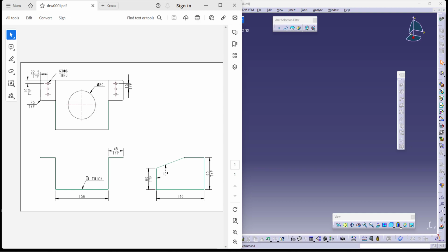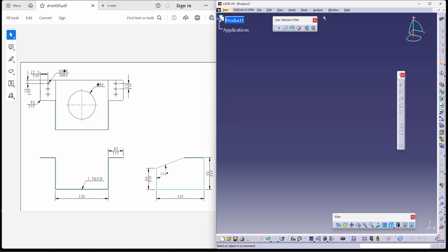So the sheet is actually of one thickness and the overall size is 160 by 140, and there are two other walls which are added, 190 by 60, and small walls over here for clamping purposes. Now, to begin we have to consider firstly our primary wall. A primary wall is usually the one which controls the complete sheet. So in that concept, the base will be the primary wall for me. So let us begin making this very simple model using CATIA.